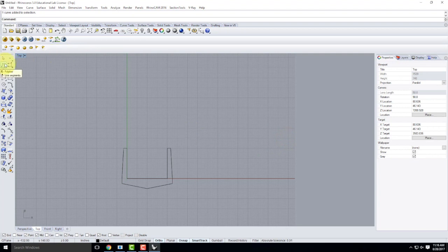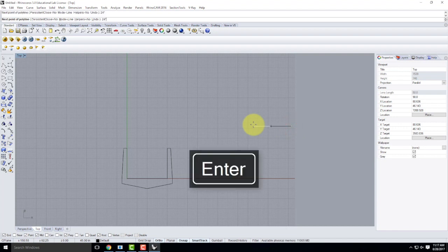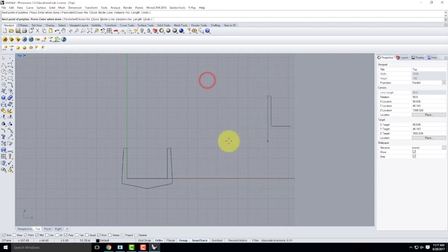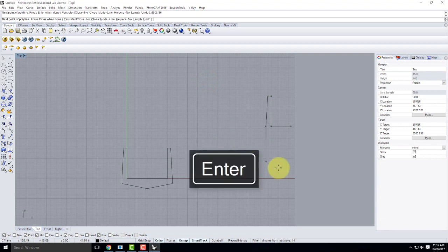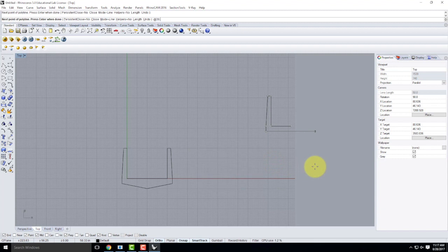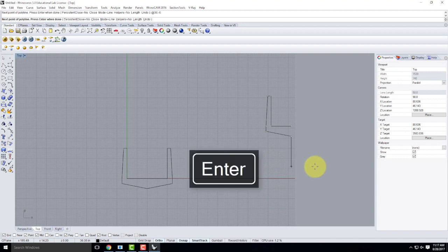But I could draw just part of the object too. So I could start, say, at 24. I'll go up 36, over 4. Same thing at -2, comma, -36. Down 6, at 30, comma, negative 6. And that gives me half the object.